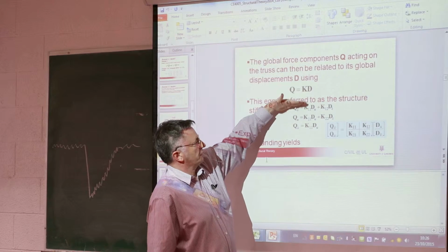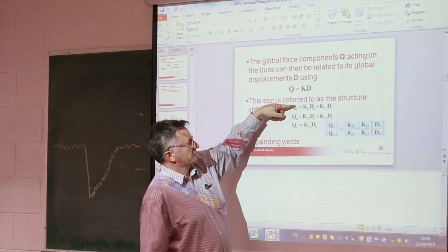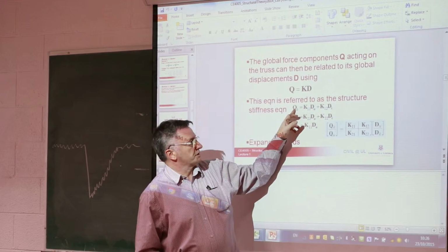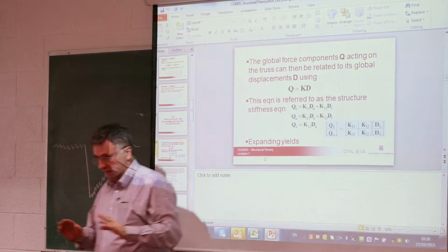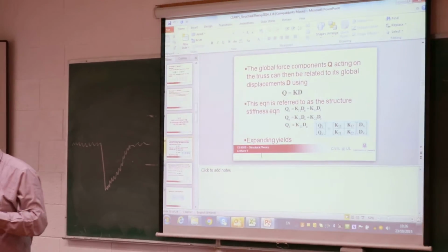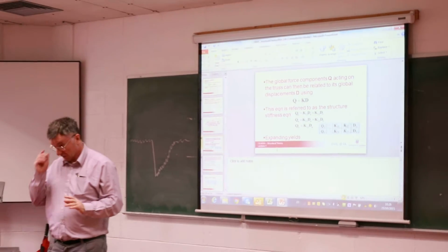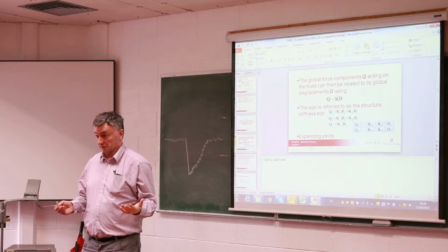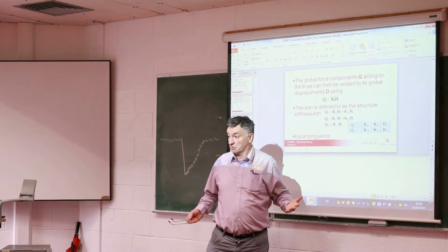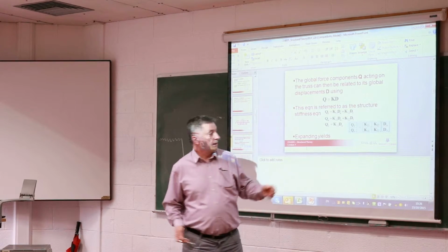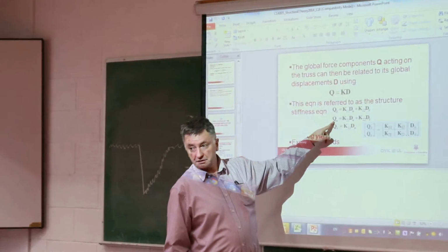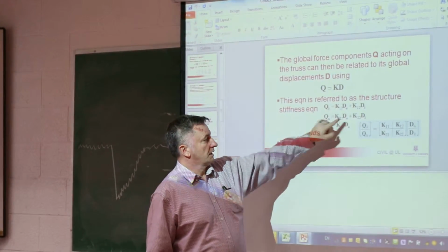We'll have one bunch of equations that relates to those nodes where we know what the nodal force is. So in other words, this top equation relates to the non-support nodes, right? Any node that's not a support, we know in principle what the load is. We couldn't solve it otherwise. I mean, as engineers, we have to know what the loads are on our structure. And whereas this one relates to the support nodes.